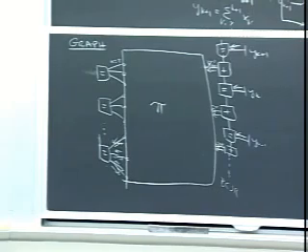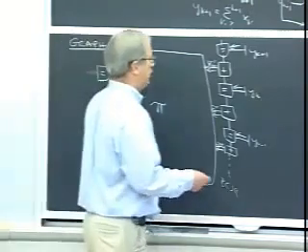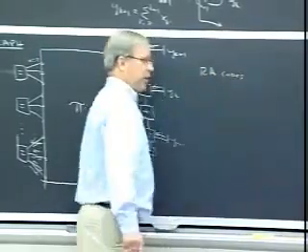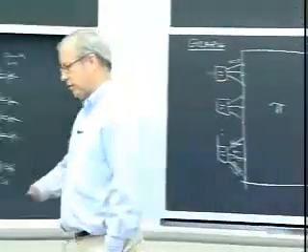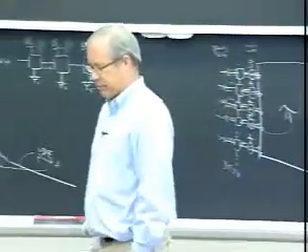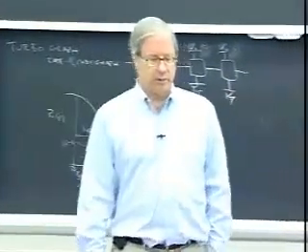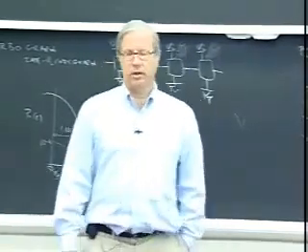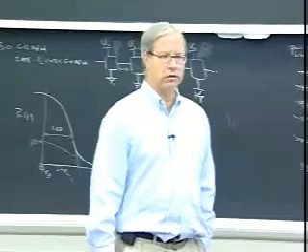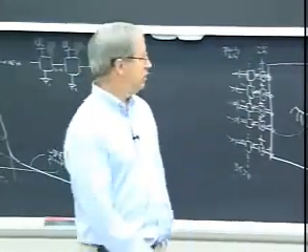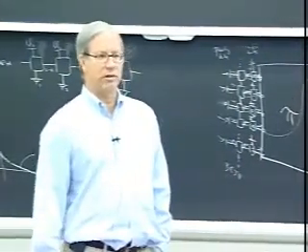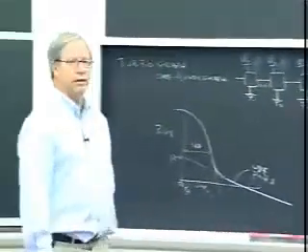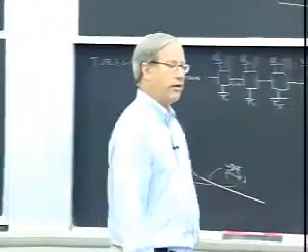So, to me, the more important thing about these, which are called RA codes, is that incredibly simple codes can do better than concatenation of a 1,000 byte Reed-Solomon code over GF of 2 to the 10th with a 2 to the 14th state Viterbi decoder. That doesn't do as well as this crummy little thing does. Okay, so that's good to know. All right, any questions?